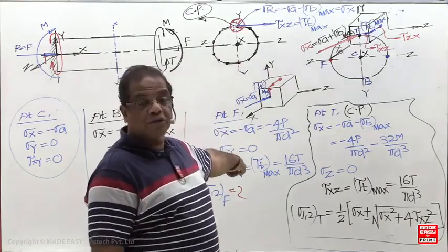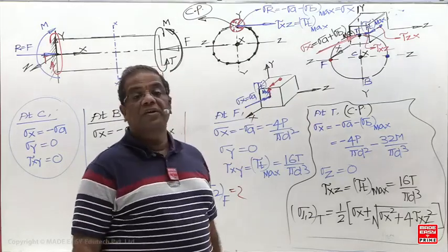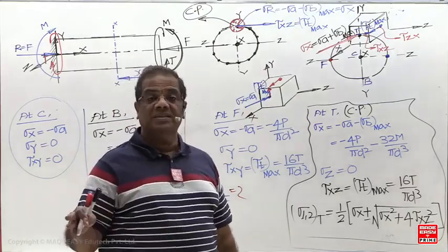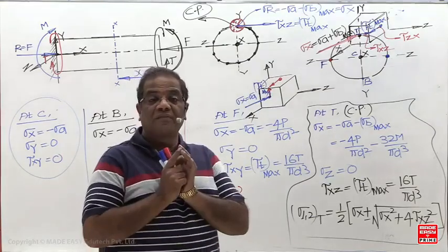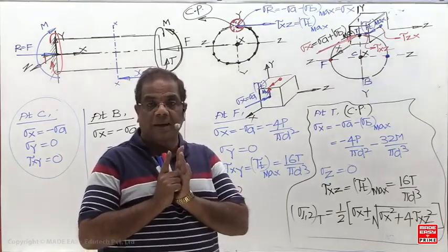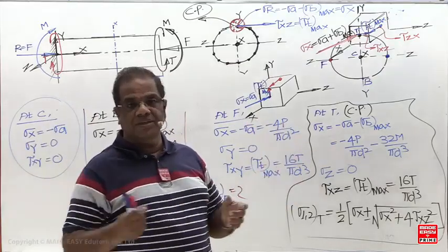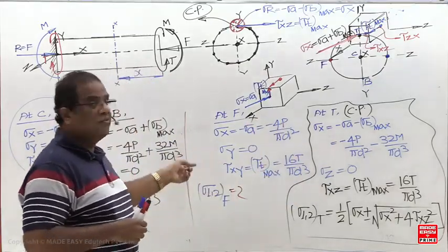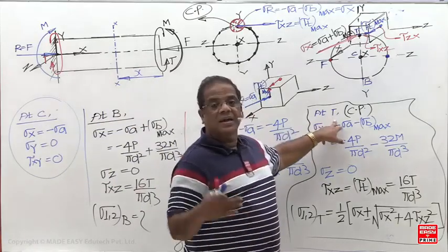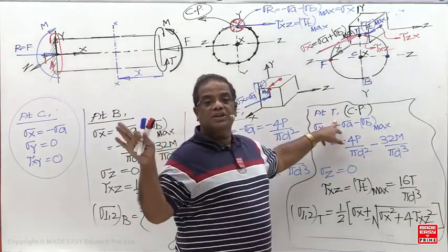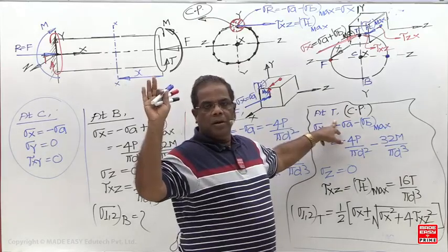That's why this type of question is not discussed in the principal stress chapter, because for this one we need axial stress variation, bending stress variation and torsional shear stress variation. By default I am taking vertical bending. Suppose horizontal bending is there, then the point is going to change. Sometimes they will ask the question; if nothing is mentioned, you have to calculate the critical point.